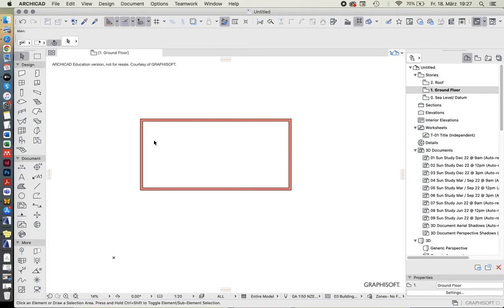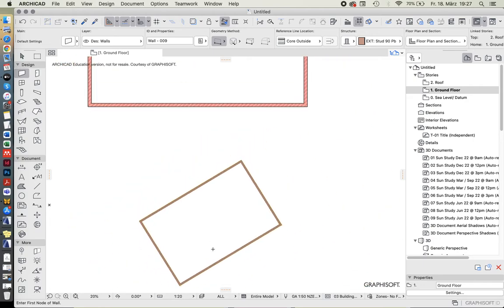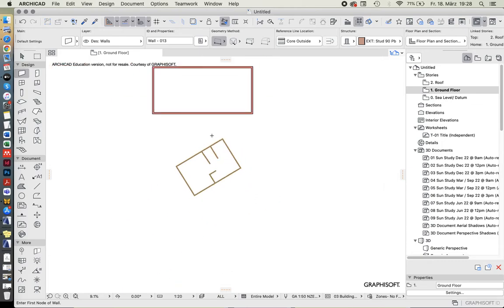That becomes really important if you have, let's assume, a building that is not exactly oriented north-south. And now if you have to start drawing these walls on the interiors, it becomes quite a bit annoying because you always have to draw them at a certain angle. Not very fun to do, and you might accidentally have slightly tilted walls. You can see in that tiny little info box, it says your angle is now at 92.5 degrees. It looks close enough to a right angle, but it's not. So it's really, really annoying.